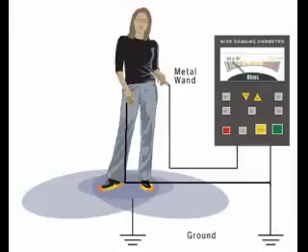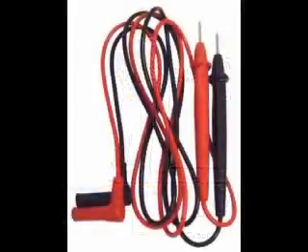Note, be careful with the probes as they are often sharp. Hold the probe tips along their length, not at the very points. You may need to adjust the meter range as your body resistance tends to be greater than 10,000 ohms. Try wetting your fingers with water and remeasuring the resistance with a meter. What impact does this have on the indication?